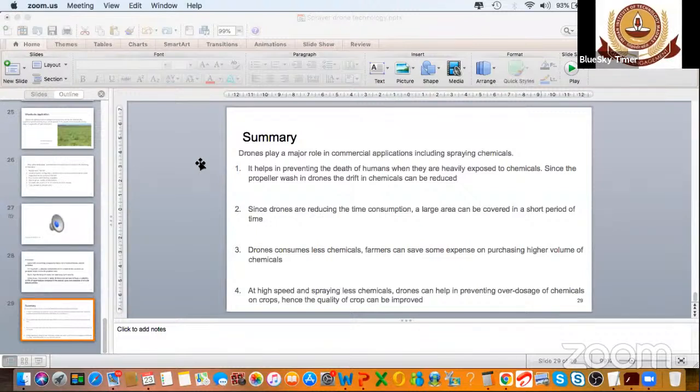And so what we try to do is to make an autonomous version of the flight. As I said, we have a geofencing, and within the geofencing, we have a path planning. The path planning is based on waypoint navigation. So we give waypoints corresponding to the RAS setting that I mentioned. When you do all that, the pilot is out of the equation. Once the pilot is out of the equation, things happen very automatically, and nothing haphazard happens. But the pilot is also required to take control, just in case there is something like a sudden gust that's destabilizing the path.